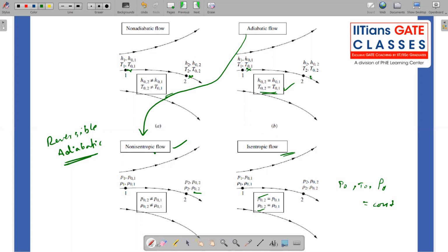Okay, this is the point I wanted to discuss in this video, that is, stagnation properties. How do we define stagnation properties, and what are the misconceptions we have? The main misconception is that we always define stagnation temperature or such properties as something which the flow reaches when it comes to rest adiabatically or isentropically. That is not the full definition. You have to start with a steady, inviscid, no body forces, and adiabatic flow field.